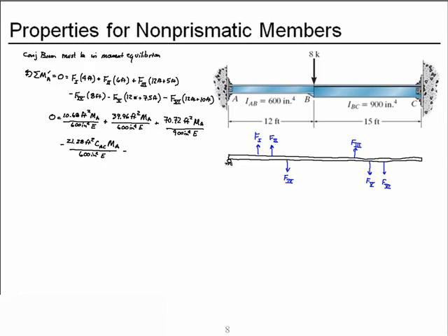And we subtract force 5 times the 19.5 feet, which is 129.87 feet squared, carryover factor, moment at A, divided by the 900 inches to the fourth times E, and our last term, force 6 times the 22 feet, and that is 91.74 feet squared, carryover factor, moment at A, divided by 900 inches to the fourth times E. Well, if I consolidate these terms, I'll have to change the denominator to 900 inches to the fourth.